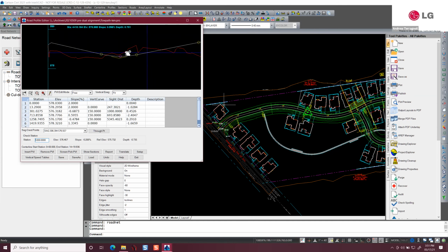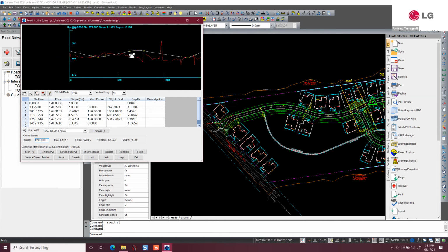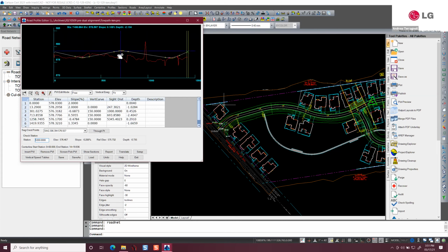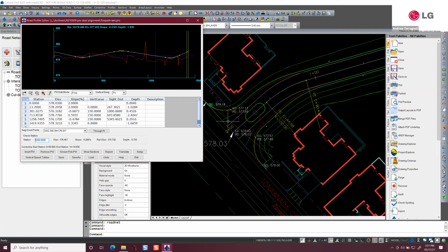What we could do is, well, I can't drain the road into the property, but I was going to get rid of the crown at the property line at station 13.2. I was going up 2%, and then I was starting the grades down so that all the drainage in the site could be self-contained, because the two catch basins on either side at 13.2 are going to drain back toward the pond.